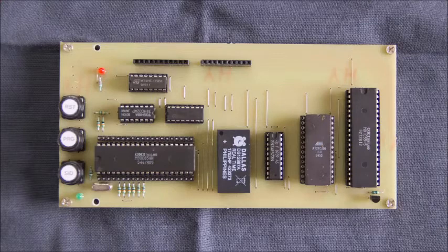The logic board of the mathematical alarm clock has various components. The main component here is the Intel 8085 microprocessor. It is the central processing unit for every peripheral IC on this board. It processes data from the I/O, ROM, RTC, and RAM inside the PPI.